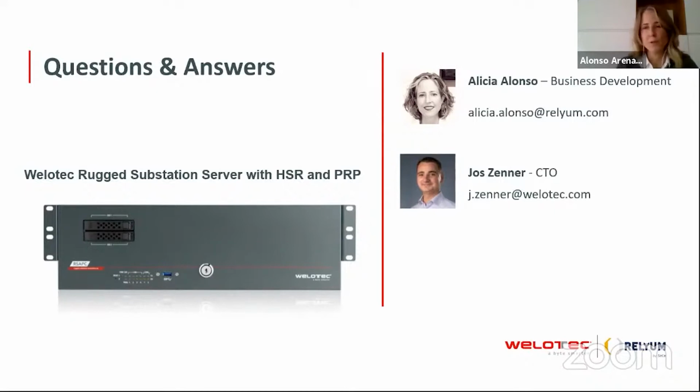I don't know if I was able to answer it. I think so. Well, if they want some information about switching latency and jitter, I don't have the information here, but I can share it. It matches very well with PTP, for example, that demands in transparent clock around 50 nanoseconds accuracy. So it's a well-defined protocol for this kind of critical systems.